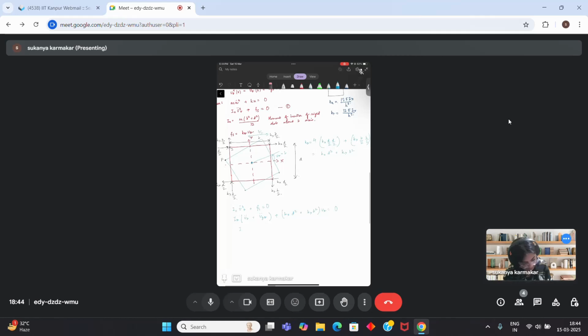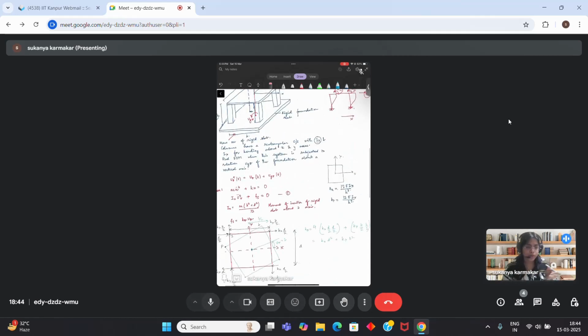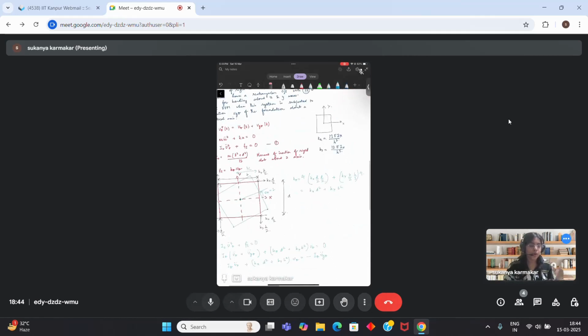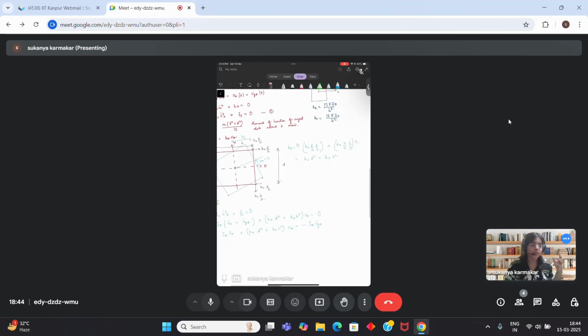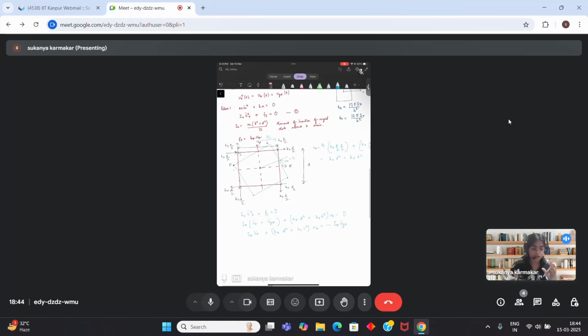So I can write this as I naught u theta double dot plus kx d square plus ky d square u theta is equal to minus I theta ug ground double dot. Similar to what we had done for a frame with a ground excitation, P effective was minus m ug double dot. On similar lines, if there is a ground rotation, then things will appear like this.